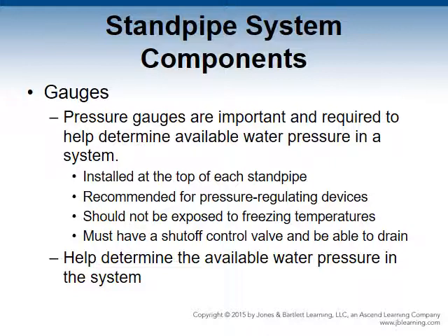Gauges. Pressure gauges are an important and required part of the standpipe system. They must be installed at the top of each standpipe. They are recommended on each side of the pressure regulating devices. They should not be exposed to freezing temperatures.